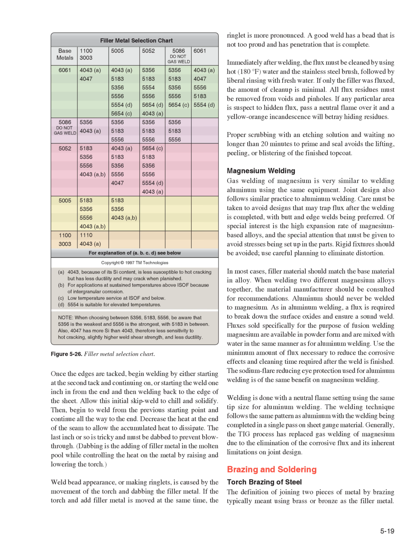Immediately after welding, the flux must be cleaned by using hot, 180 degrees Fahrenheit, water and the stainless steel brush, followed by liberal rinsing with fresh water. If only the filler was fluxed, the amount of cleanup is minimal. All flux residues must be removed from voids and pinholes. If any particular area is suspect to hidden flux, pass a neutral flame over it and a yellow-orange incandescence will betray hiding residues. Proper scrubbing with an etching solution and waiting no longer than 20 minutes to prime and seal avoids the lifting, peeling, or blistering of the finished topcoat.